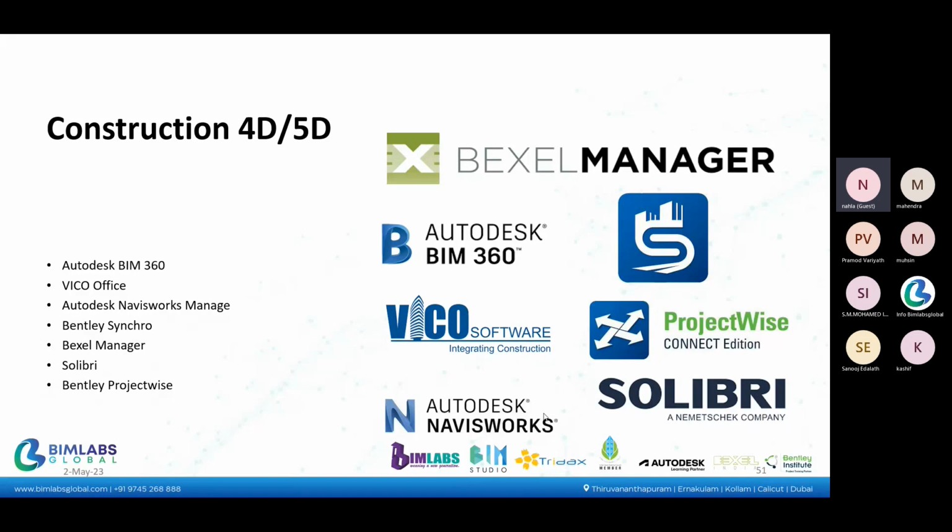I'll just tell you a small example. There are BIM 360 field and layout apps. If there is any defect on the site, the site supervisor can take a photo and upload it in the app, and the other officials or the people who did the model can review the issue and advise solutions. Thereby, the problem can be resolved on the spot itself.